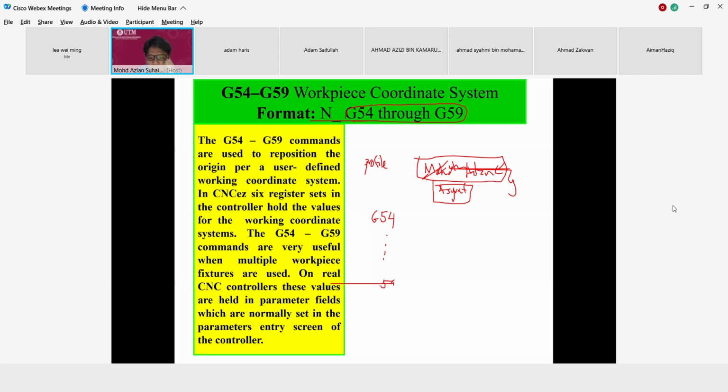So you can save different profiles, G54, 55, 56, 57, 58, around 6 profiles. Let's say you use G54. You have all your settings, your favorite settings in the machine. So every time you use it, you should include G54. Let's say your friend wants to use this machine, she should use G55 lah. Otherwise, he will destroy or usik kacau awak punya setting lah. Awak tak nak macam tu lah. Kan awak tak suka lah.